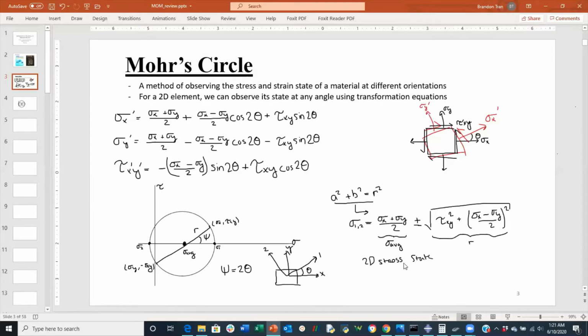Okay, so I mentioned principal stresses as the radial components of the Mohr circle that don't have shear stress. Essentially, the whole idea is we can boil down the entire stress matrix into essentially 2 equivalent stresses. For a 2D case, it will be 2 equivalent stresses. For a 3D case, it will be 3.